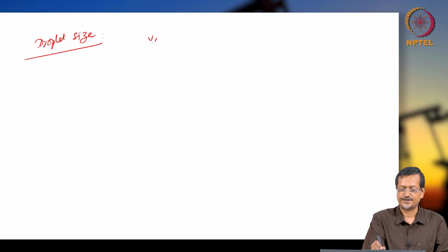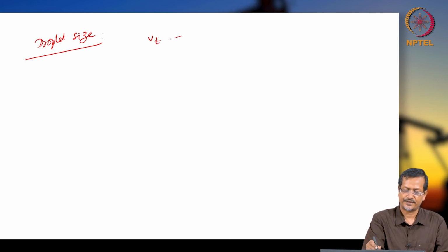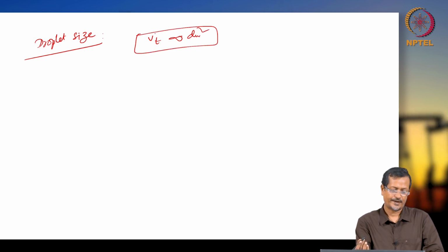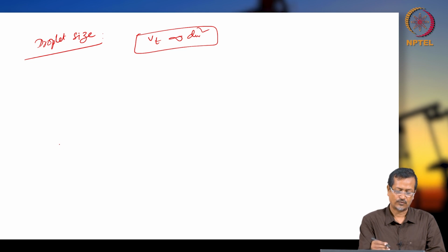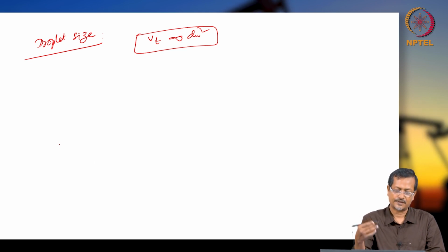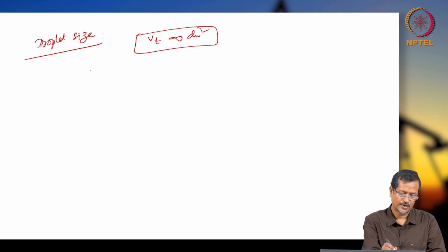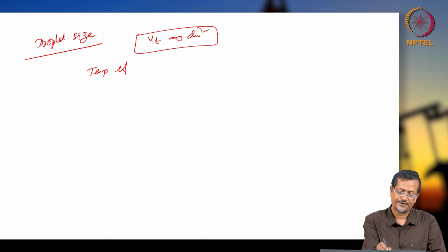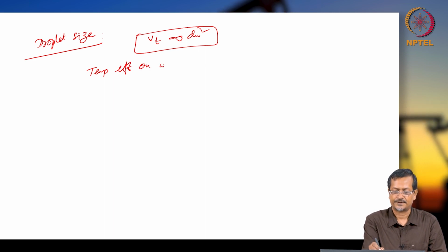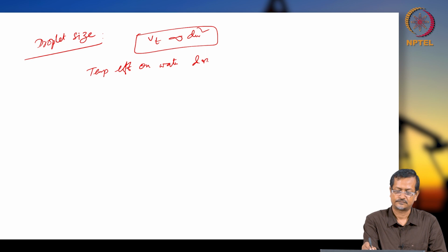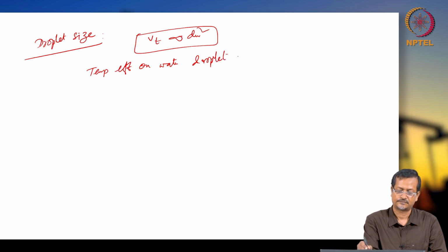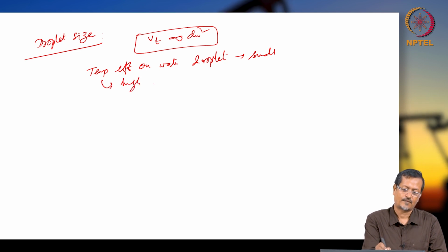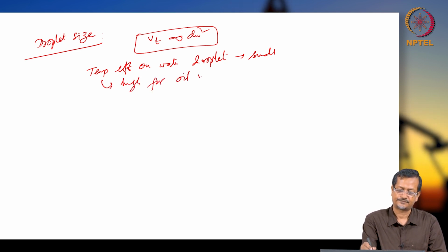Last topic of this one is droplet size. Already you have seen Vt is proportional to dm square. Okay, so high particle size means the settlement rate will be high. So the oil-water interface zone, where all coalescence normally occurs, is assumed and it happens also. The temperature effect on water droplet distribution is small, but it is high for oil viscosity.